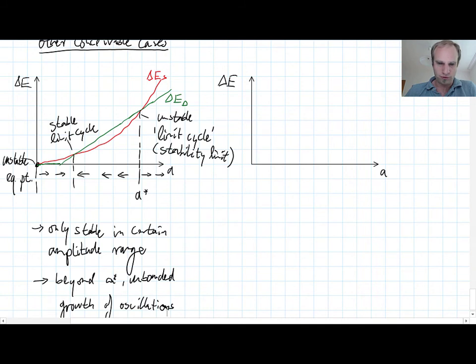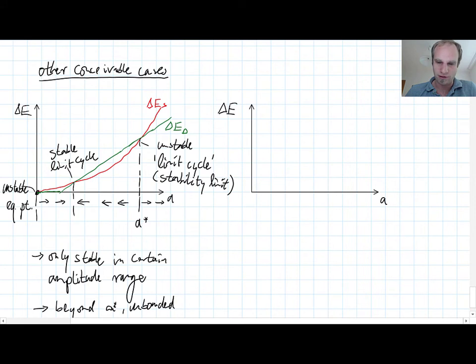Now this is not just a mathematical abstract example, but actually this is quite relevant, because this delta ES is nothing special. This is just a negative damping. Negative viscous linear damping leads to precisely this quadratic parabola shape of the supplied energy. And the dissipated energy, you might already see that this corresponds to elastic dry friction. So something that we already discussed.